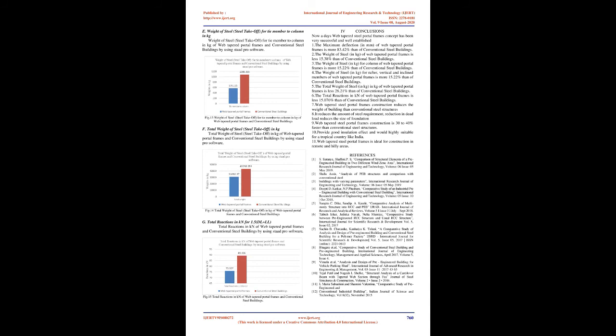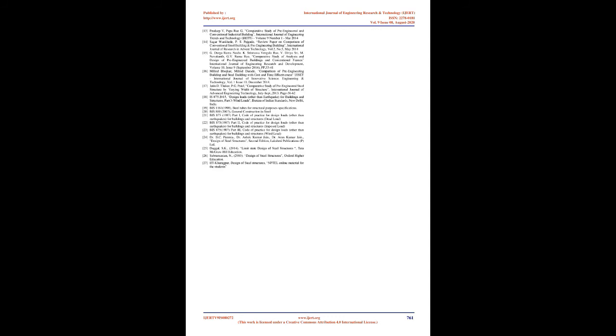G. Total reactions in kN for 1.5 DL plus LL. Total reactions in kN of web-tapered portal frames and conventional steel buildings by using Staad Pro software. 4. Conclusions. Nowadays web-tapered steel portal frames concept has been very successful and well established. 1. The maximum deflection, in mm, of web-tapered portal frames is more, by 83.42%, than of conventional steel buildings.